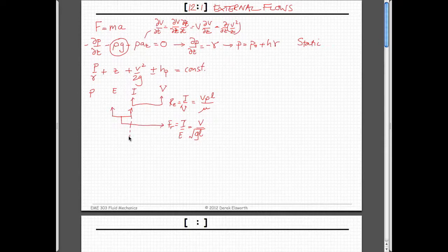And we also looked at the ratio of the inertial forces and the pressure forces. And that's an important one to us because this is what we've referred to as the Euler number. It is the ratio of the pressure forces to the inertial forces. And you'll recognize the number. It comes out to be something like a fluid pressure divided by, what is it? Density of the fluid times the velocity squared, just that. And we can also write this as a force. If we call the force P, uppercase P, instead of a pressure, then it's density times the velocity squared times an area. So force over area is just equal to pressure, right? That's all I'm doing. So those were three important forces that came out.